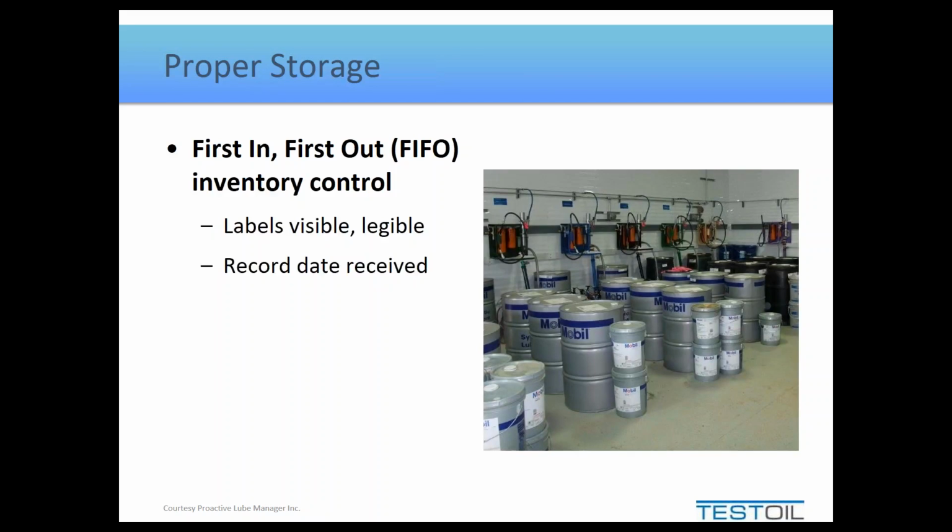Now, because you've got the rack-mounted filtration there, it has a pump, because that's what's circulating the oil through the filters. Well, that pump is what you can also use to then suck from the drums and fill your oil fill containers, whether they be pails or oil safe containers or whatever it is. So a lot is being accomplished by a fairly simple setup, but you will notice that there are several rack-mounted filters because there's one for every type of oil. And that way it prevents cross-contamination between products.